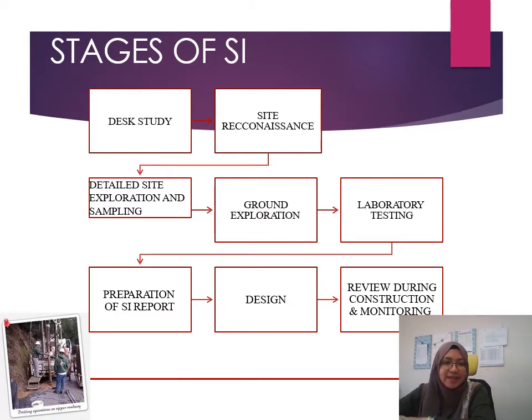Okay, next is stages of site investigation. It doesn't matter whether your construction is big, moderate, or small. For all construction work, you have to conduct the SI. So these are the stages of site investigation, starting from desk study. Desk study means that you gather all of the information and then you analyze that information.